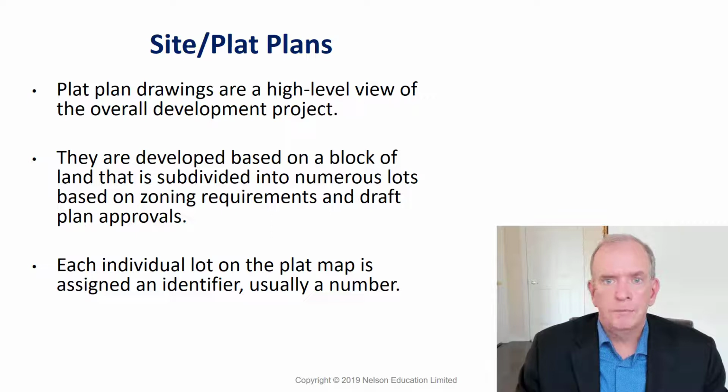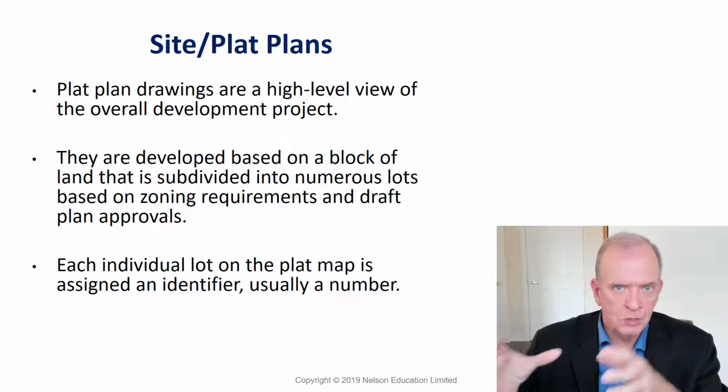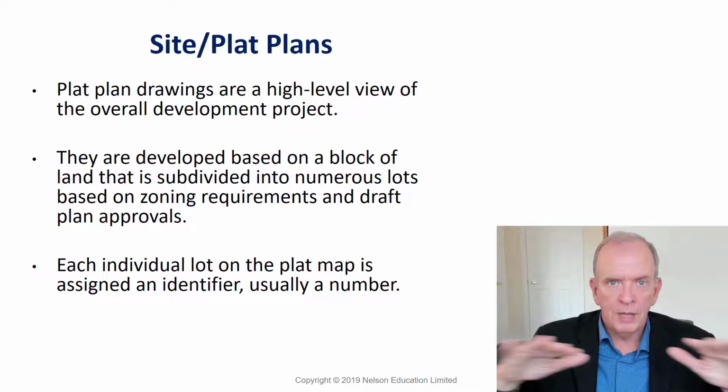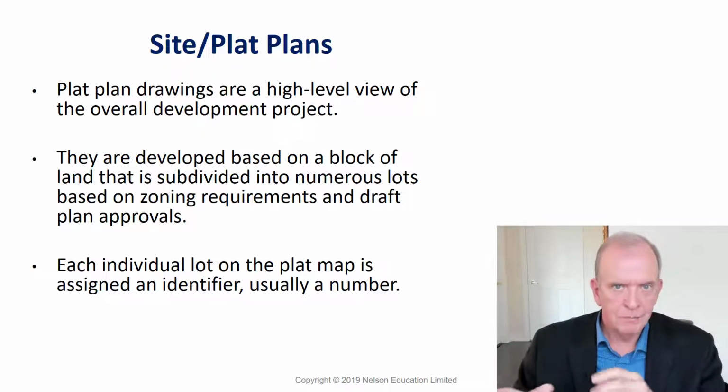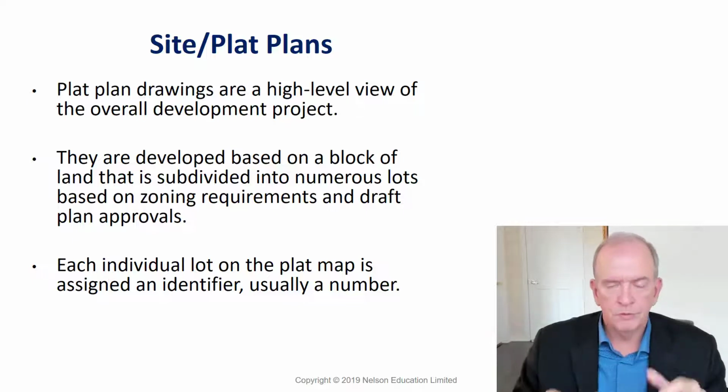You might have a plat plan for a series of condominiums going in a huge field that might be empty right now, and they're going to build it in phases, and each condominium is going to have its own legal description. So you might have an overall plat plan of how everything works together, but then you'd have individual site plans and surveys, legal descriptions for those particular properties, because the condominium corporation would have jurisdiction over those particular properties.